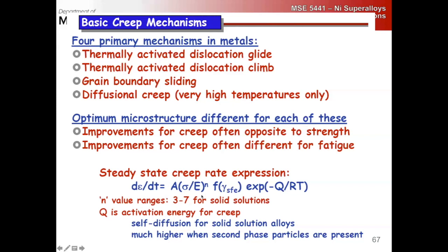If you're really keen on understanding the physical origin of this stress exponent, I just published a paper last year where we did a model where we put a backstress in here. We showed that with the appropriate backstress from dislocation interactions with the gamma prime, we can reduce the stress exponent down to the mechanisms that are predicted for solid solution strengthening. So this high exponent for superalloys is really a function of the dislocations interacting with the gamma prime particles, right? But I don't want to get too much more into the details on it than this.